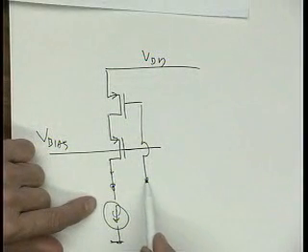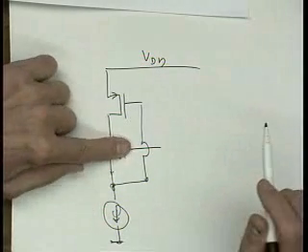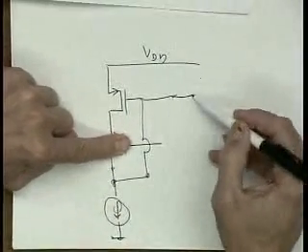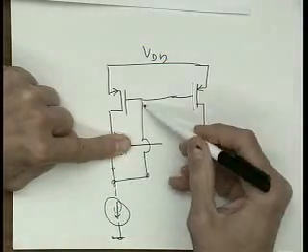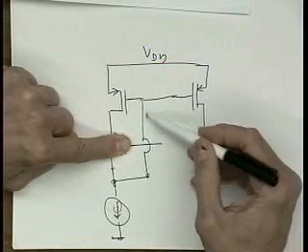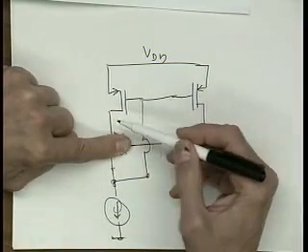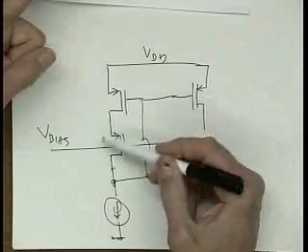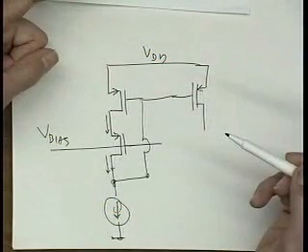So what is this thing doing when I tie this off here? If you didn't have this transistor here, what is this? And this is going over. So this connection is really just a diode connection of this current source load. Okay? So I could have done it right here, but I sort of made it do double duty. I put this other transistor in here. The current here is exactly the same as the current here.